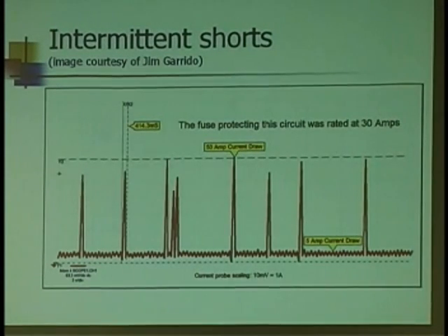How does a fuse work? It's a thermal device, right? It has to heat up. So you turn that back to your customer. Maybe your buzzer didn't pick it up, your bulb didn't pick it up, but your scope will. And I can set the trigger to go off when I hit that peak, when I hit any kind of current flow.